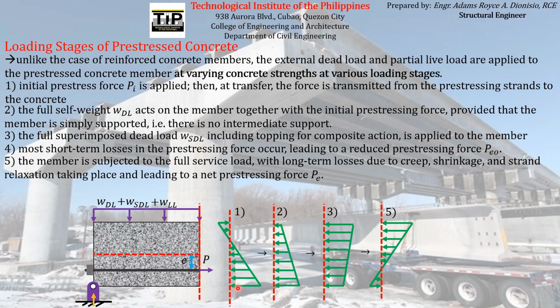So from being a compressive stress, it has lesser and lesser magnitude until it actually reaches a tensile stress. Just like what happened on the top fiber: from being tensile, it experienced an increase in magnitude, and it became a compressive stress with a larger and larger magnitude up to this particular stage of loading of the concrete element.